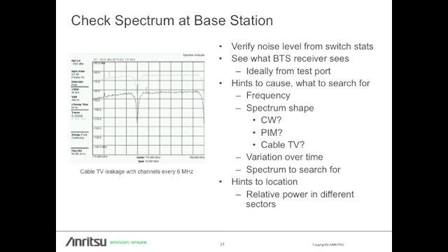You can also see variations over time, maybe what time of day or what day of the week the signal's causing a problem. And you get a picture, and so when you're out in the field, you know what to look for. And you can also get some hints to location here, looking at the relative power in different sectors.